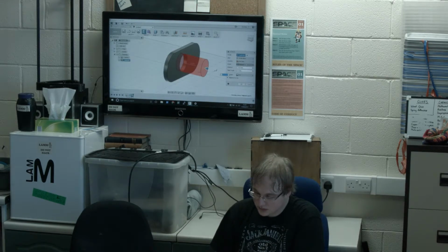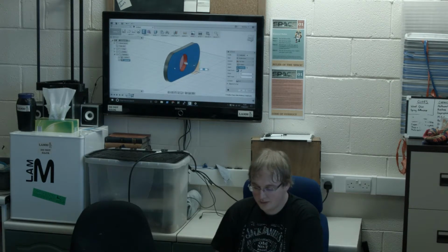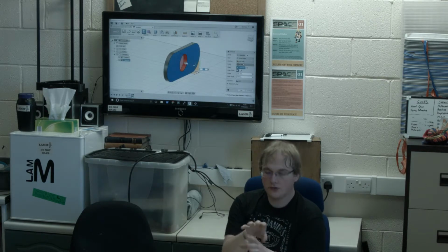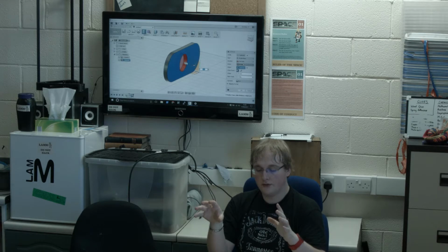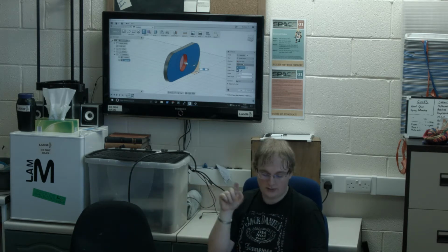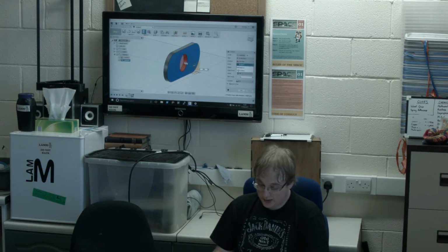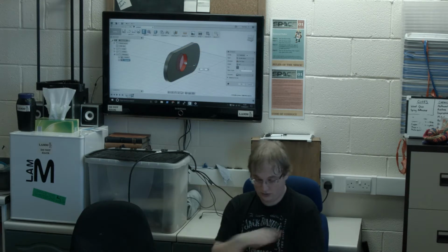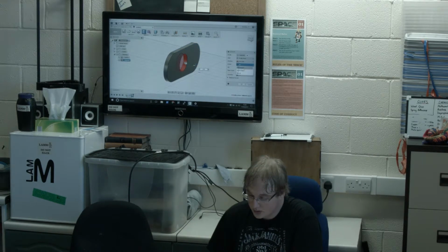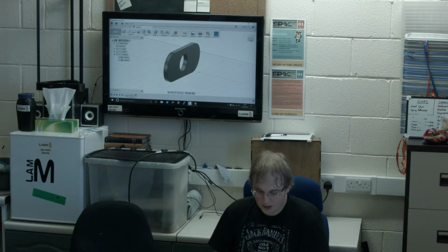So if you do change the extent to object, click the other side, that's now a hole through the whole thing. And this works with multiple selections. So if you've got 8 holes you need to go all the way through as one operation, just select them with control, click through, done. You can also just say all, which just cuts a hole. But to object I find is suitable for that. And there we go.